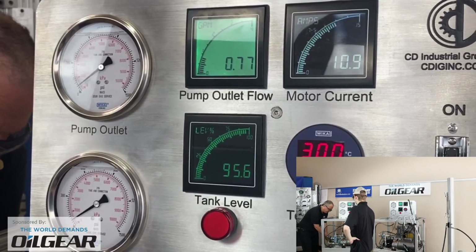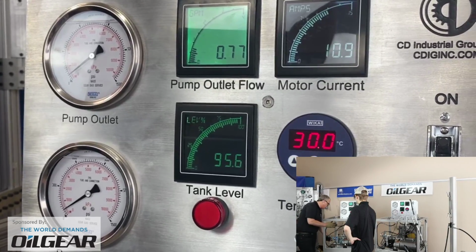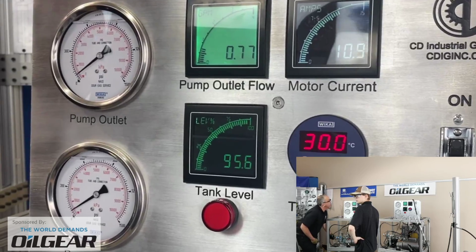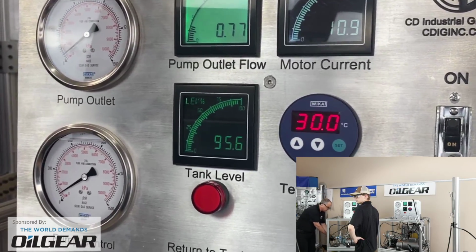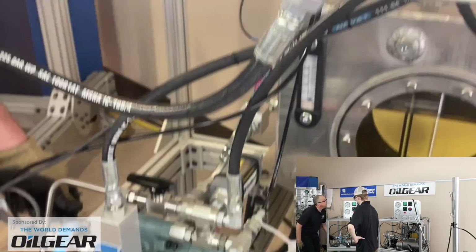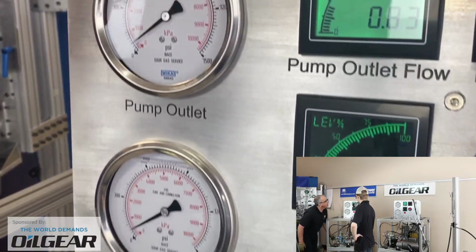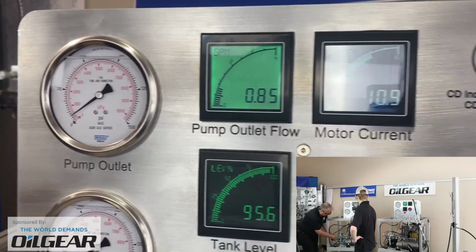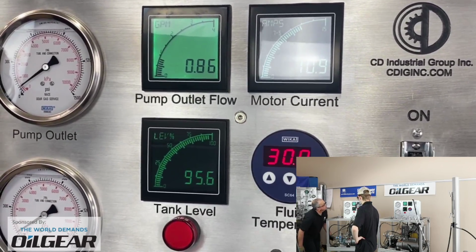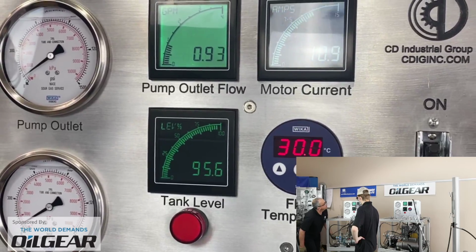So which way do I have to turn the adjustment screw? Well, with one of these axial inline control pistons, which are very atypical design, typically to make the pump larger, one needs to turn counterclockwise. This is an adjustment that's lower down on the cap end of the pump. And I'm just going to turn counterclockwise and find out that our pump flow rate, as being measured through a WebTech turbine flow meter, is increasing on the display, 0.91.